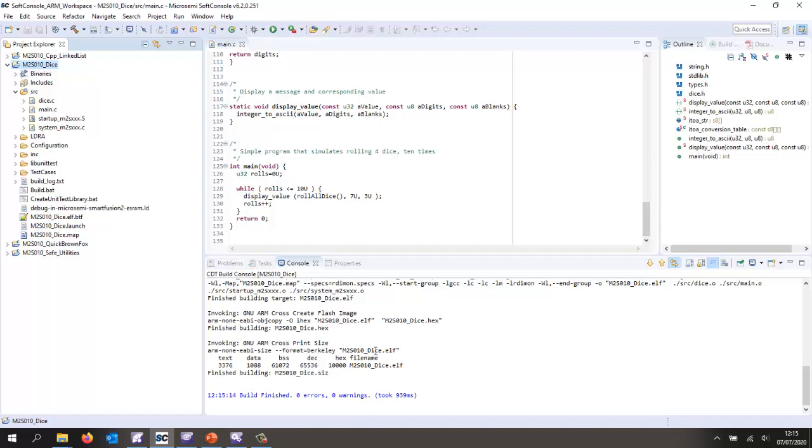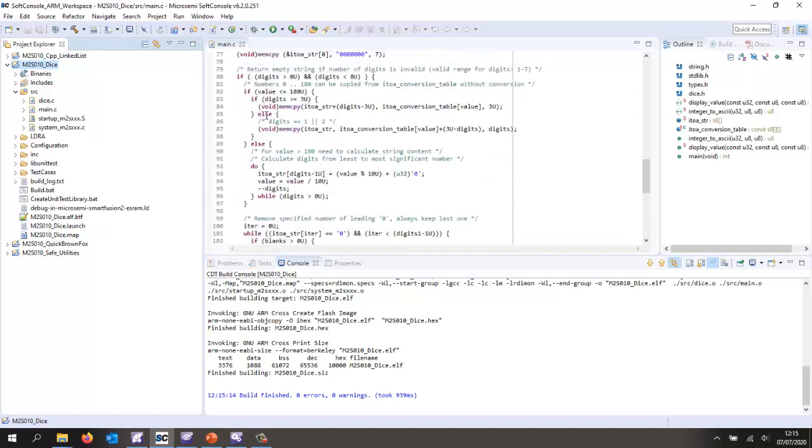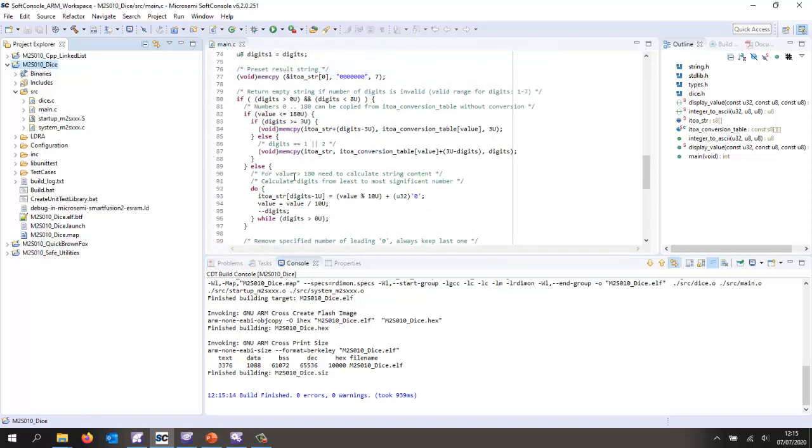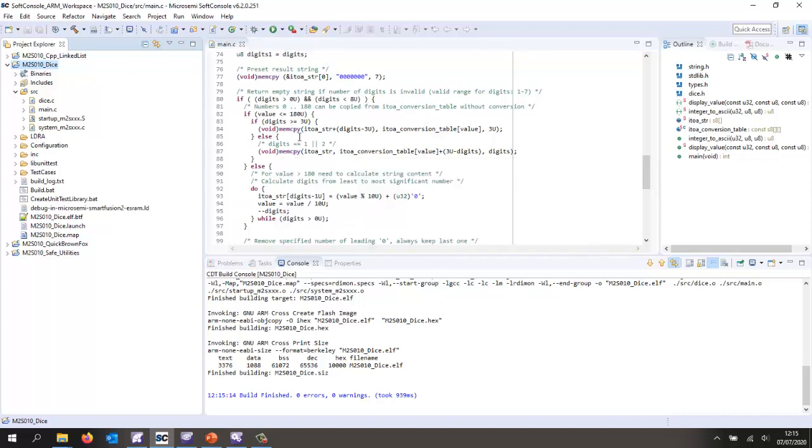Now what I'd like to be able to do is first of all examine this code and see, well, is it compliant to a coding standard such as MISRA 2012? I'd like to be able to look at the code and measure some metrics on the code, such as the cyclomatic complexity. I'd also like to be able to execute this code, and as it executes, I want to find out which parts of this code have we exercised and which parts have we not exercised. And then I imagine we won't have full coverage for this, so I'd then like to use the unit testing tool in order to complement that coverage.